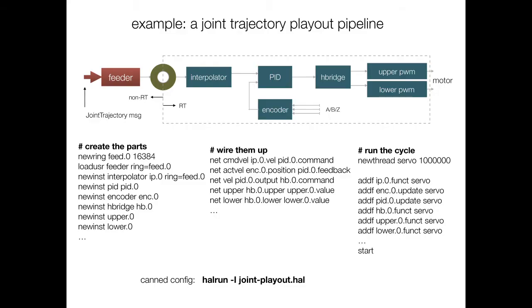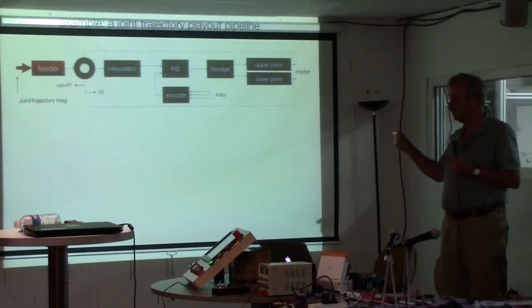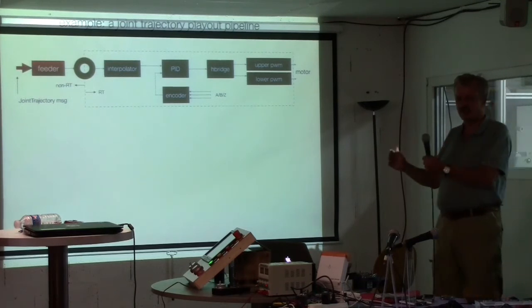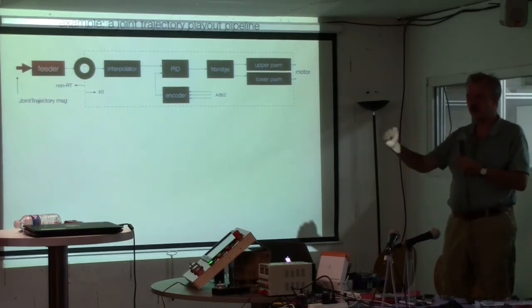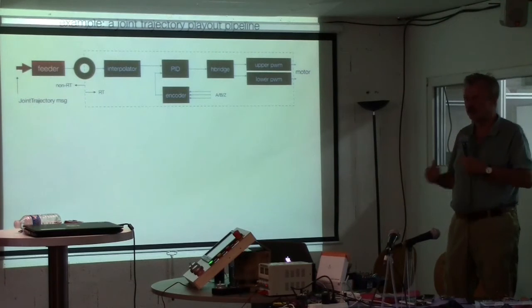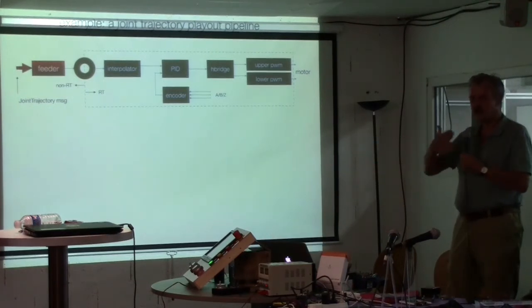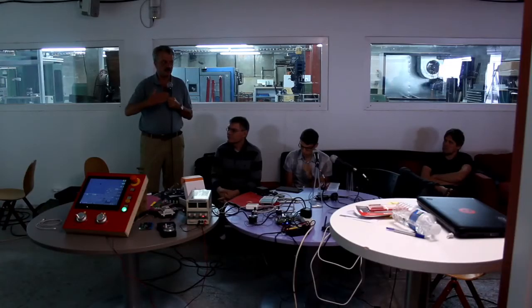It's typically line segments or arc segments or Béziers. And that is handed over to hardware. There's one of these curves for each joint, and they're played out in parallel to the hardware. Okay, and that is a process which is rather time critical because it introduces noise otherwise into the process.